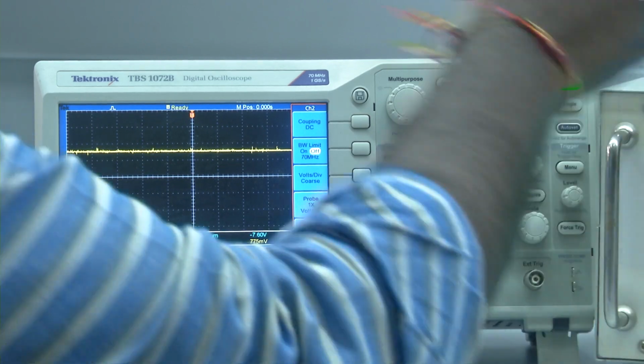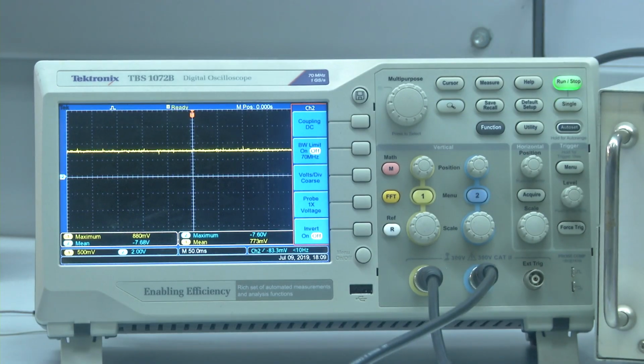provided we cannot go more than 1.2 or 1.3 volts, because if you go more than 1.2, 1.3, then the output voltage, since the gain is 10, will go to 12 to 13 volts. Since the plus VCC and minus VCC of the operational amplifier here is 15, above the saturation voltage, whatever may be the output, it cannot be represented. So the maximum output voltage the op amp can show is only till the saturation. That saturation entirely depends upon the power supplies being provided for operational amplifiers.